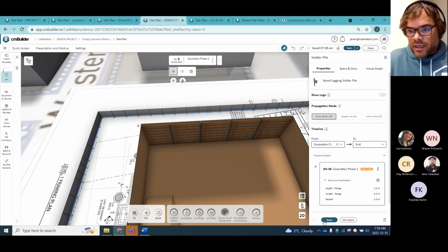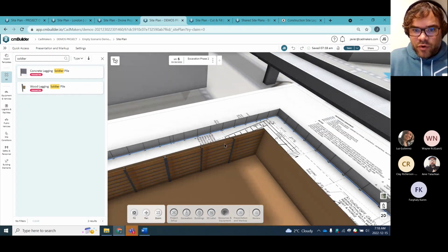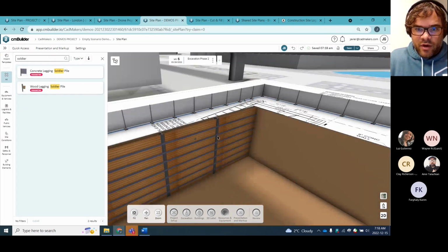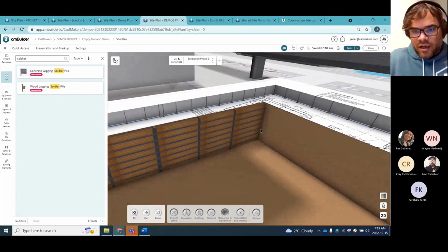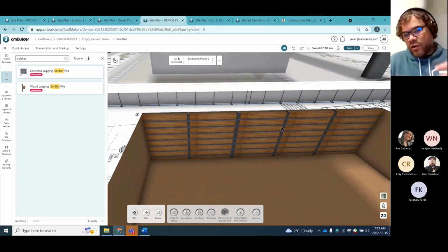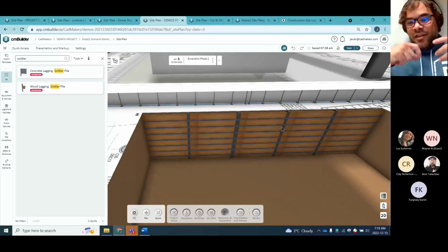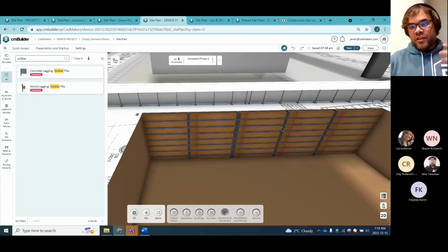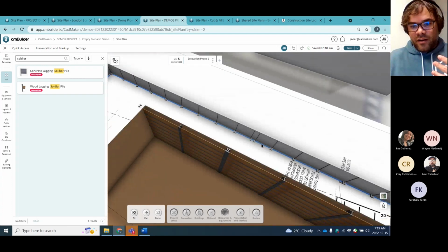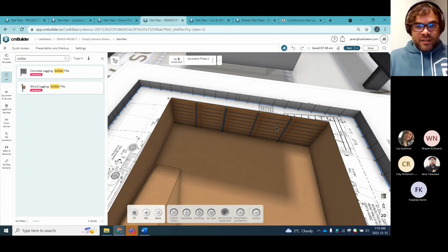So it's a fully parametric resource that you can manage from here. Really dead simple. But let's say you're going in pre-con with the client. You want to be able to say, hey, what's it going to look like schedule and cost-wise to vertically shore this with a shotcrete wall, et cetera. Or like we've seen before, a customer recently said they couldn't get an underpinning agreement with the owner on the other side of the property. They wouldn't let them do underpinning under their property. So the geotechnical engineer came up with a very complicated raker system.